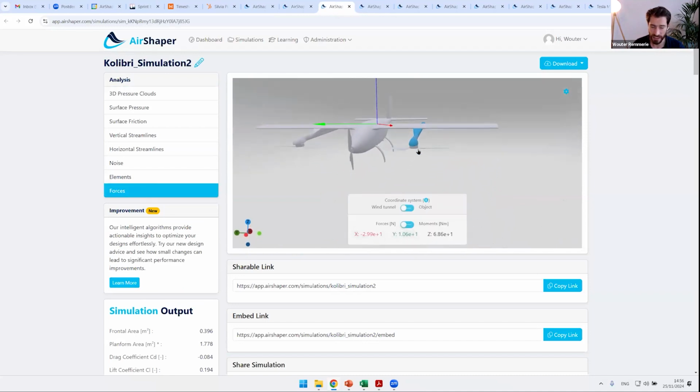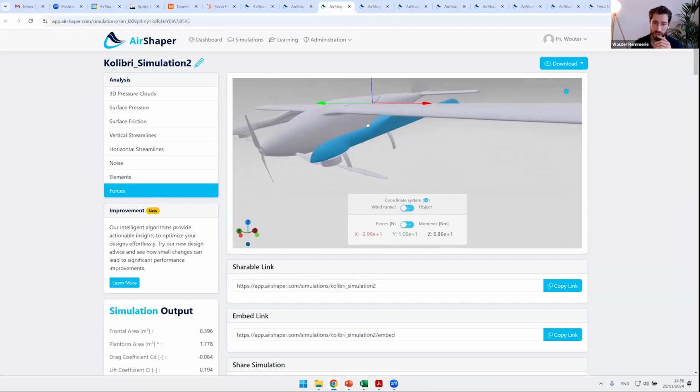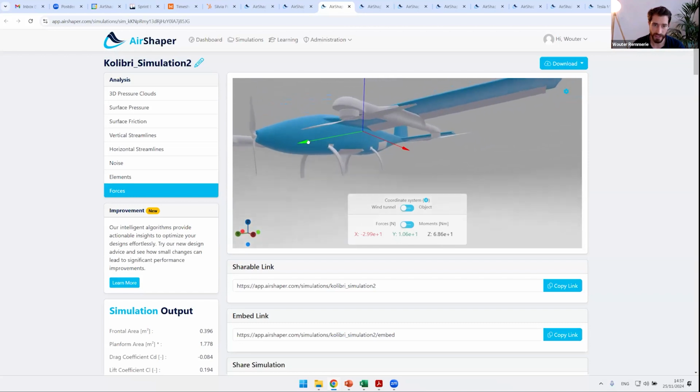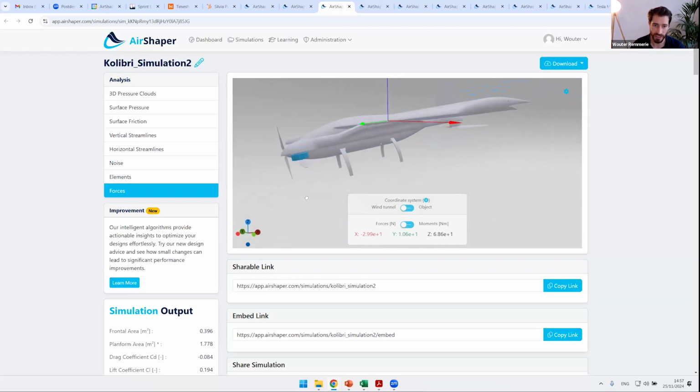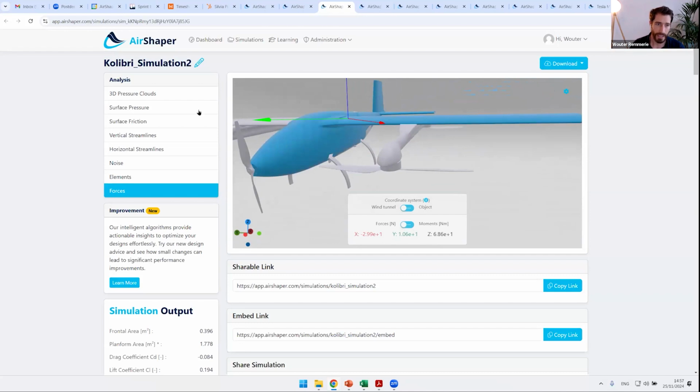This is easy, but if you're looking at an application like this, these propellers are actually very close to the support element here. That means if you would build a cylinder around it to create this moving reference frame, it would cut or interfere with the static part. And if you don't solve that, you get all kinds of completely unrealistic flow. So what we've done is to create an automated method where this revolved object for the moving reference frame fits nicely around the static elements without actually touching them, so the user doesn't have to do this.